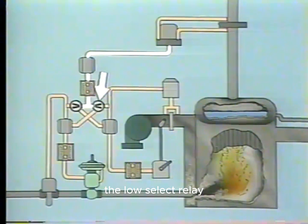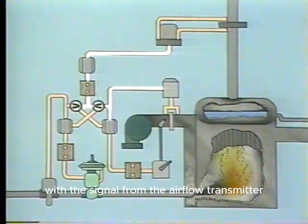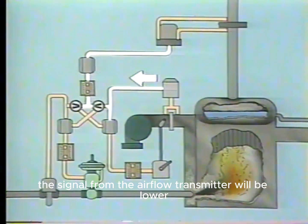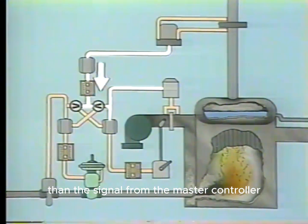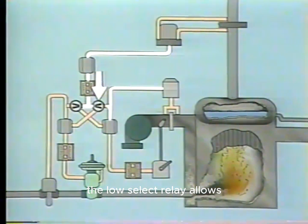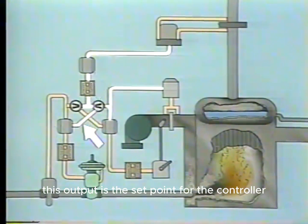The low select relay compares the signal from the master controller with the signal from the airflow transmitter. At this time, the signal from the airflow transmitter will be lower than the signal from the master controller because steam flow has increased but airflow has not. Therefore, the low select relay allows the output from the airflow transmitter to pass through it to the fuel flow controller. This output is the set point for the controller.